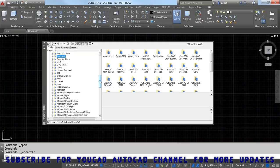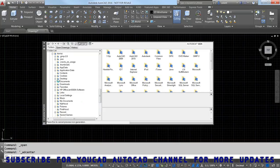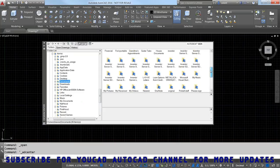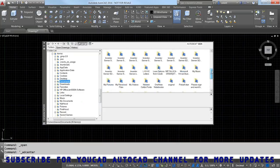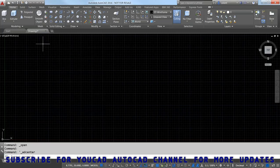I had a customer just last week who said, if I go to C:\Users, my username, and go into Documents, I'm not seeing any drawing files. But if I pull up the My Documents shortcut in Windows Explorer, I see all kinds of drawings. That's when we drilled down and found out that their Documents folder was indeed redirected. You can still get to those same files with the Design Center. You just have to know specifically where they are.